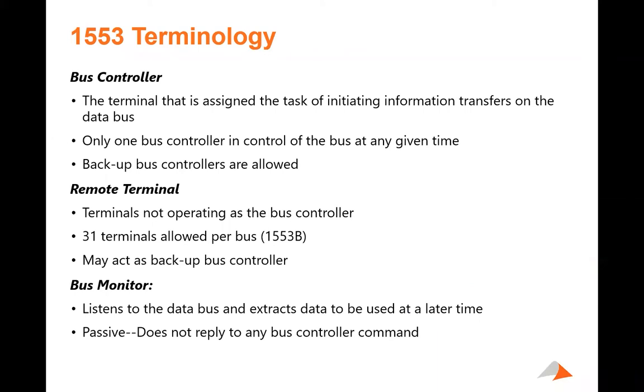All right, some basic terminology that I've already touched on. The bus controller is a terminal that is assigned the task of initiating all information. Bus controller, like the rest of 1553, are software controlled. The bus controller, the remote terminal, the monitor are part of the terminal of an LRU, and then you have the subsystem of the LRU, and we'll see that in a drawing to understand it just a little bit better.